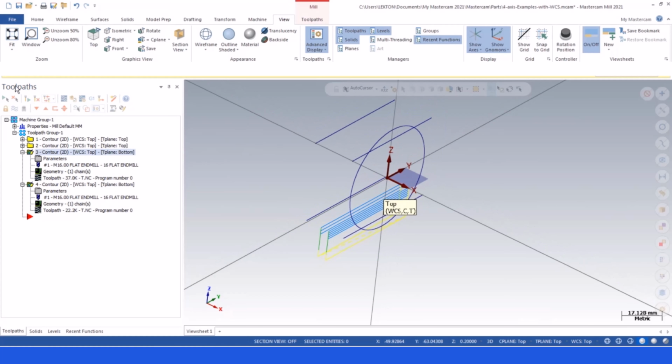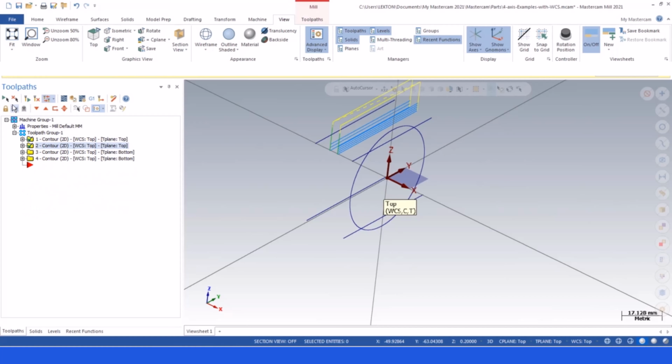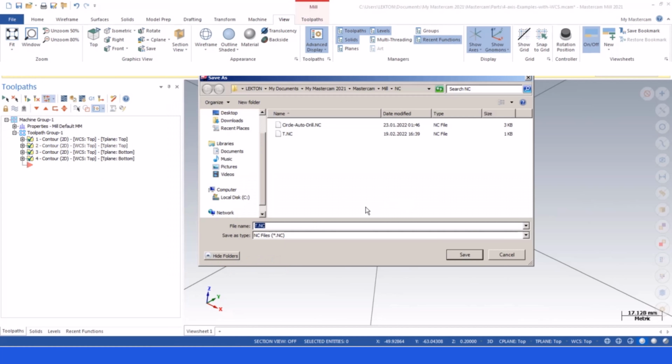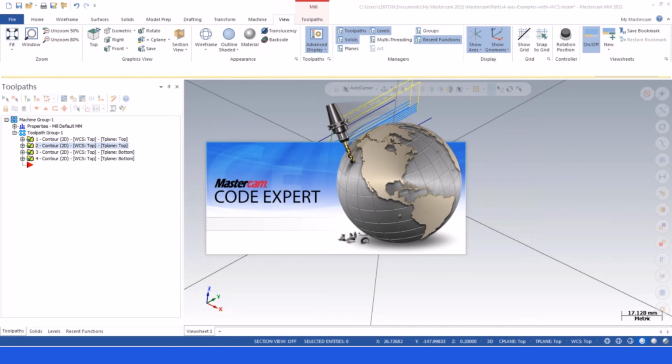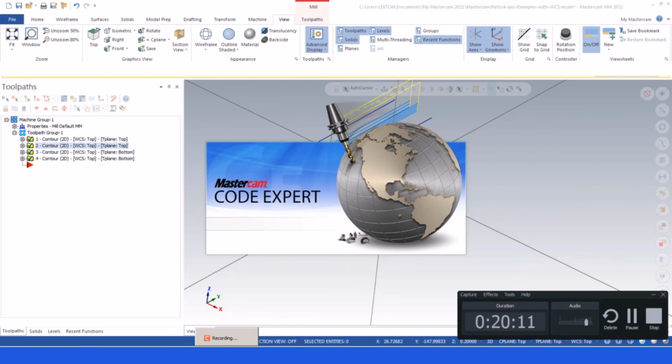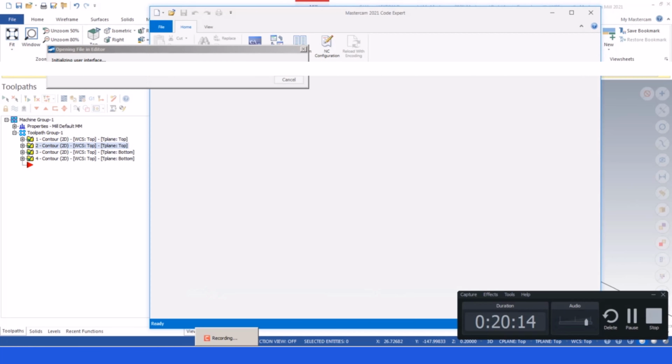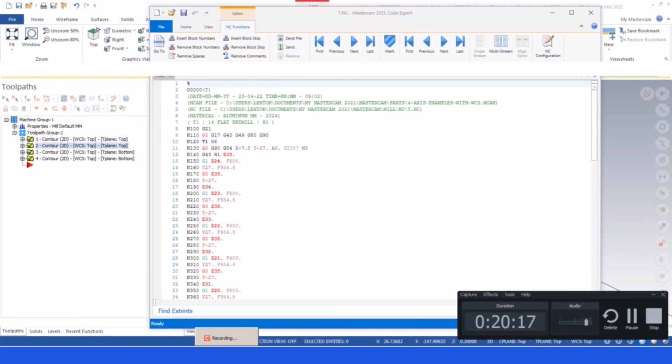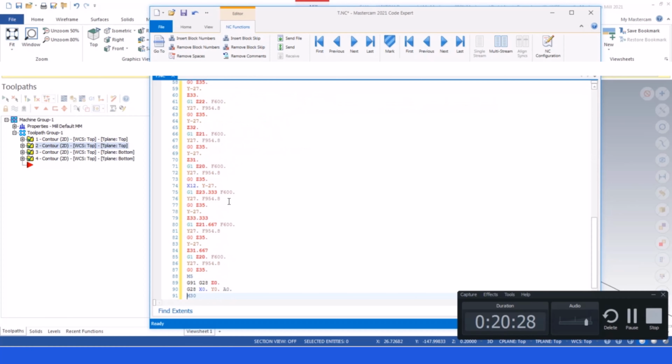So everything seems fine. This is my toolpath. This is another toolpath here. Okay, let's see our keyboard here. I can select all my toolpaths and push the G1 button according to MP1 or Fanuc control unit, and you're gonna see our keyboard here. Okay, and let me check our code right now. Remove, and maybe we also use the remove block numbers here.